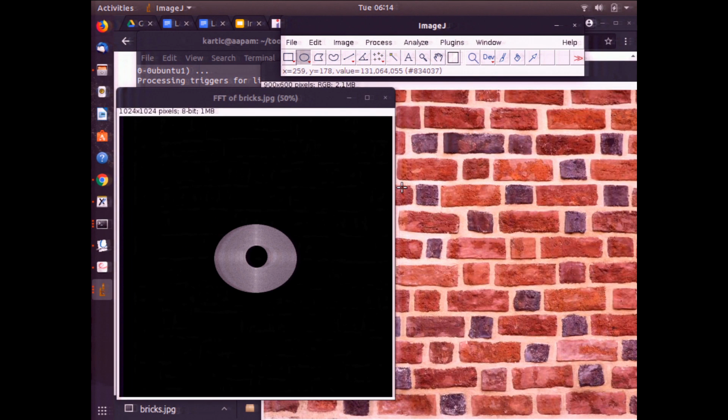So now you see you've applied some filter. This is what signal processing people call a filter, where you've removed low frequencies, you've removed high frequencies, and you've got this band. You can think of your filter as a traffic policeman on the highway, stopping any vehicle that is smaller than a certain size and any vehicle larger than a certain size, right? And that filter which does this blocking is called a band pass. You're selecting which band to pass, and it's called a band pass filter. If you remove just the center, people might call it a notch filter.